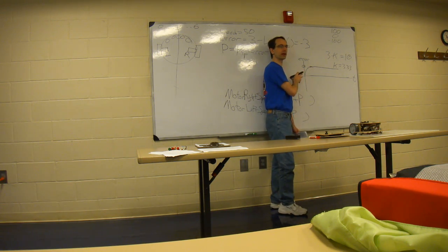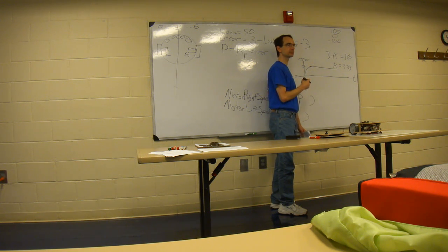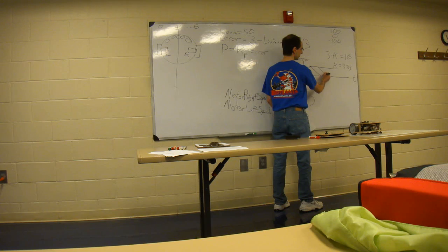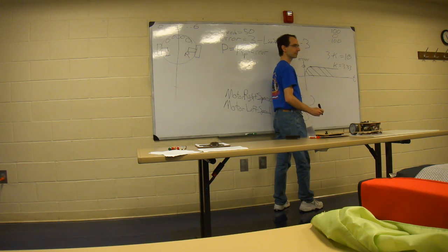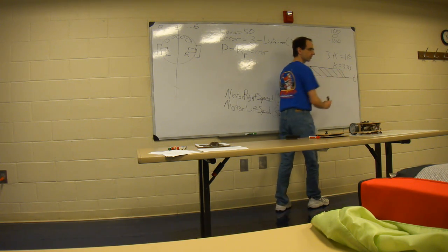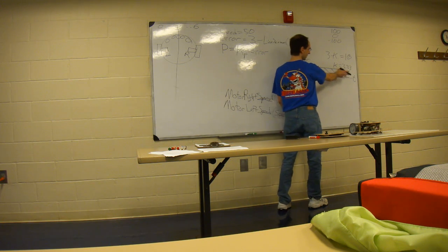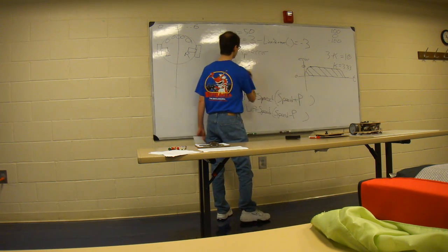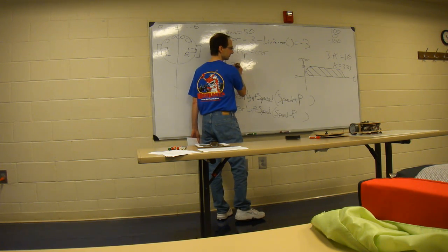So what is changing on the graph? Does anybody see what is changing on this graph? Time. Well, time is always changing, but that is a component of it. What is actually changing here is the area under this curve. Because once the error falls to 0, the area under the curve falls to 0 too. So we can look to see, is the area under the curve continuing to grow? And that is our I term.